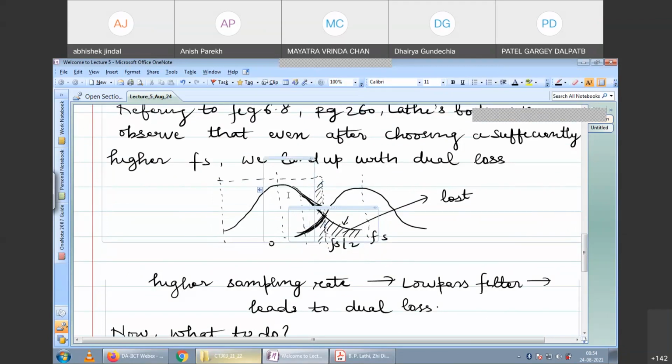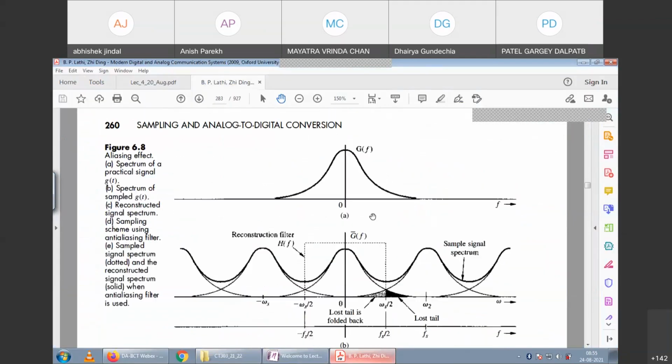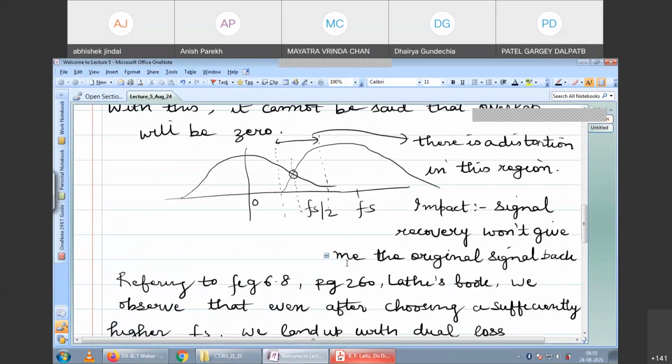So a spectrum of the sort in which high frequency components are low power. Okay, so low frequency components take most of the power. That's why we are studying this sort of signal. Because in reality, most signals are like this. That's why we can sample them easily. Otherwise, if you sample it, that's fine, but when you reconstruct it, it won't give you the exact signal back.